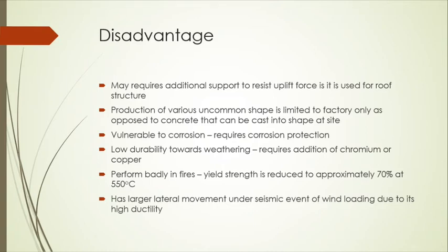And also steel performs badly in fires, if you have a catastrophic fire event or fire mishap in a structure, in a residential building. The yield strength is reduced by approximately 70% at 550 degrees Celsius.